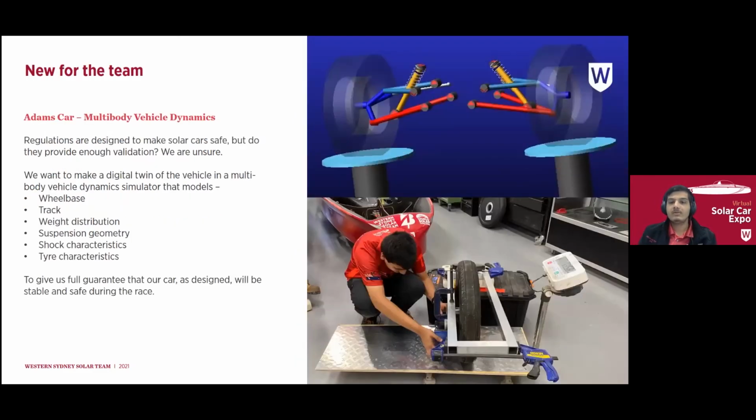Now, in 2021 and 2023, the regulations are looking to be much more stringent on stability. However, with the increased ride height requirements and the introduction of three-wheelers, there's a real ease with which car configurations can become inherently unstable. The regulators will conduct a 45-degree tilt test as a way to verify stability, but within the team, we are looking for further validation.